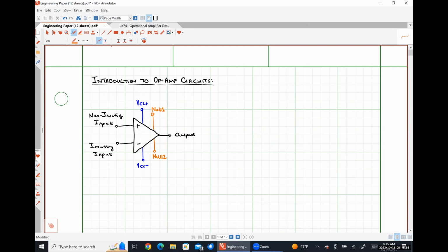So if you had the exact same voltage connected to those two terminals, the expectation should be, based on how one of these things work, that your output voltage is 0. If it's manufactured poorly, it won't be 0, and those offset pins are used to literally just recenter that output at 0. That's all those pins are used for.